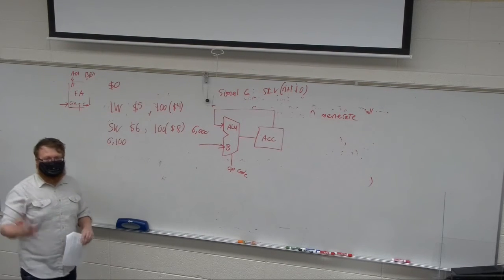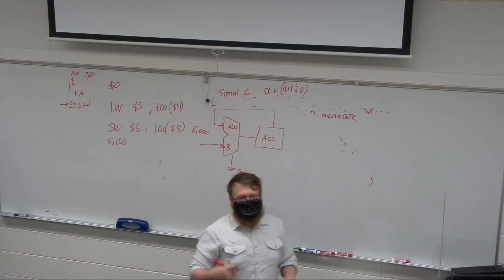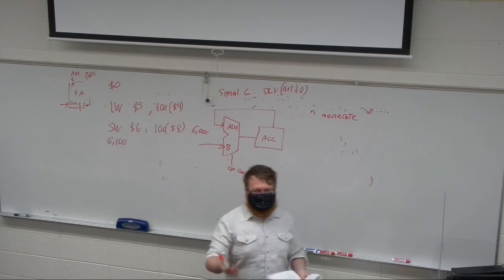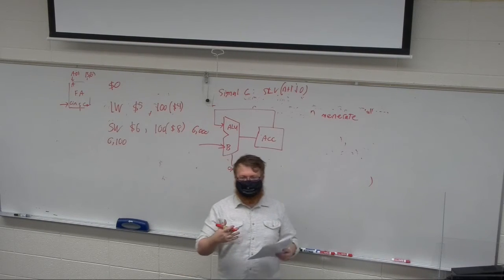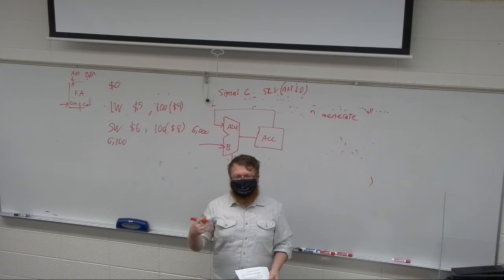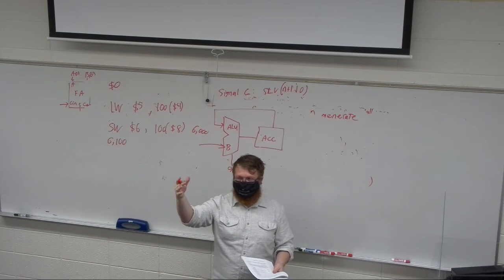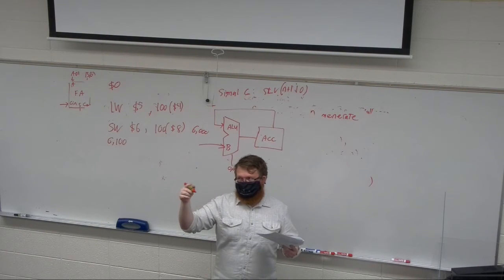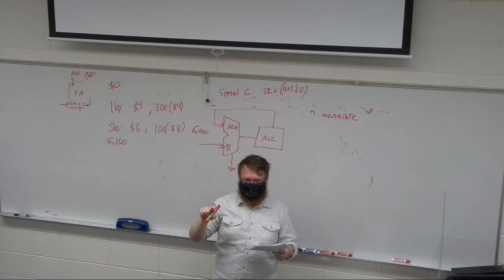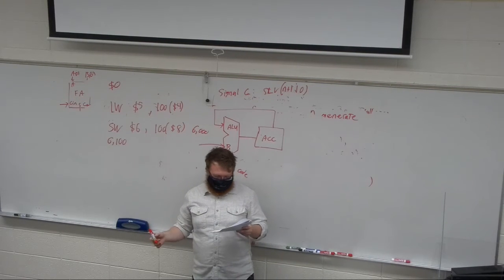Okay, so now we have to do the next annoying thing. I don't even know if you guys got to it in your 2700 lab, which is where we interrupt the process counter, right? So we have this idea of the PC, the process counter, that just tells the controller where it's at. But sometimes we don't want to take just the next instruction. We may want to jump ahead, save something, and then come back and continue. We may want to loop through something, right? To do that, we use what they call control transfer instructions.